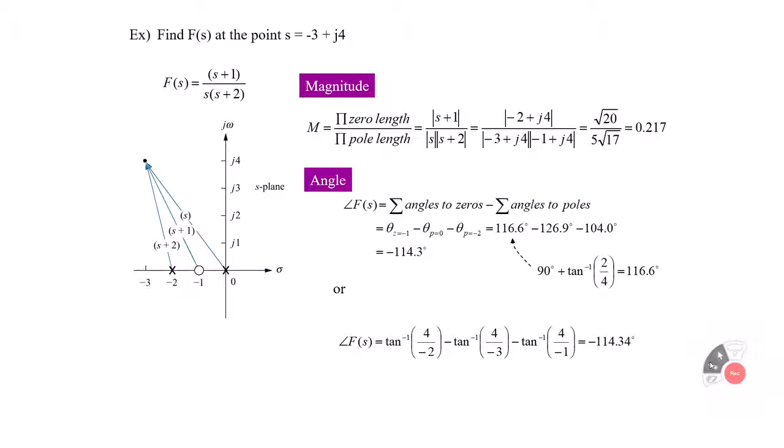So this is my function. How can I compute the phase angle of this? Arctangent of the real part and imaginary part. What about this? Arctangent, real part, imaginary part. Arctangent, right? For the phase angle, we do not use multiplication and division. We use addition and subtraction. So when you do the phase angle computation, the multiplication should be added, and this division must be transformed into subtraction.